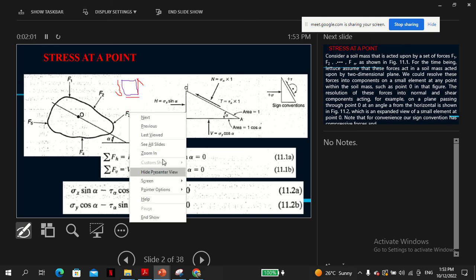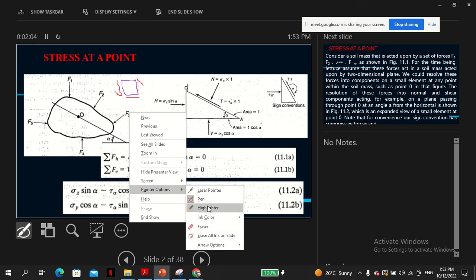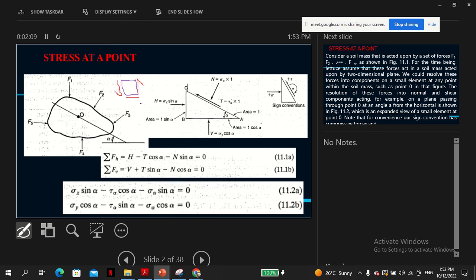I use a different color to show. So these are shear stresses that are induced, because otherwise this is the applied external load. So if it's a load from a building, whatever, that's the shear. But because the material has to remain in equilibrium, this is the reason for an opposing equal force. Now this action makes these edges not have any forces, but equilibrium has to be maintained. So because of this, there are shear stresses.